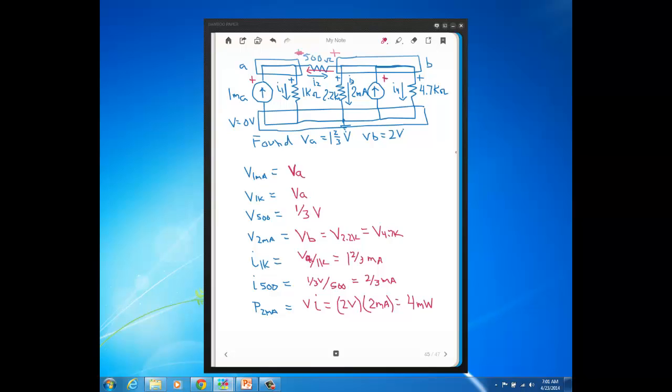So the main point of this part of the lecture is that the work doesn't stop once you have the solution to your node voltage equation. Once you solve for the previously unknown node voltages, you can then go back and find voltage, current, power for all the elements. And this is where you're utilizing concepts that we talked about earlier in the class: KVL, KCL, Ohm's law, when power is being absorbed, when power is being supplied, all those types of things. So you can't forget what we previously discussed before this method.